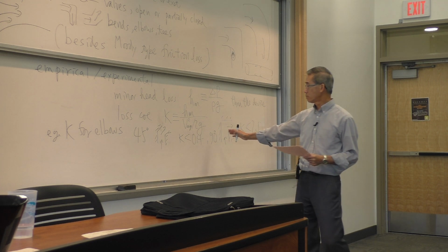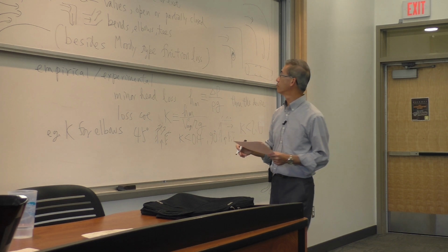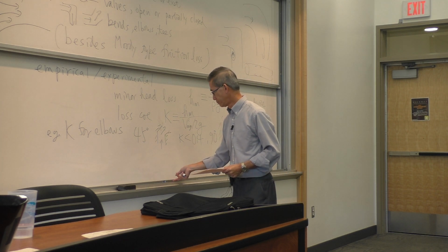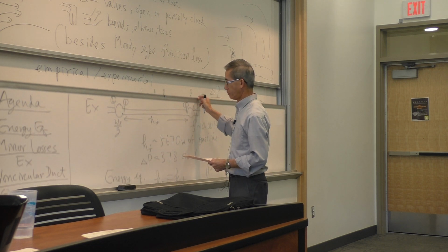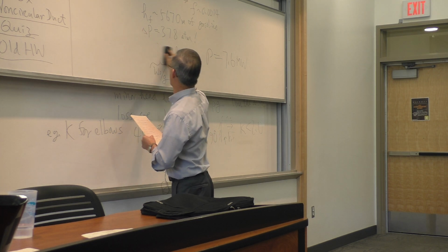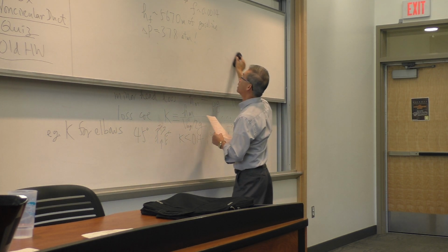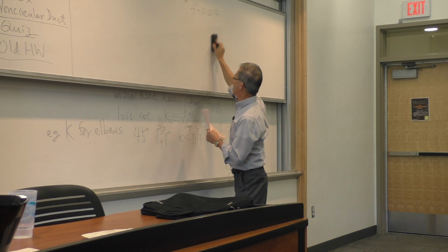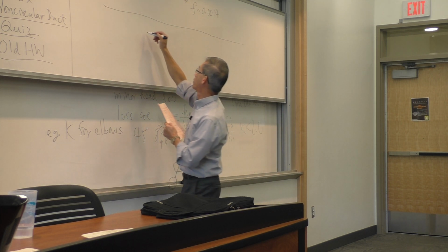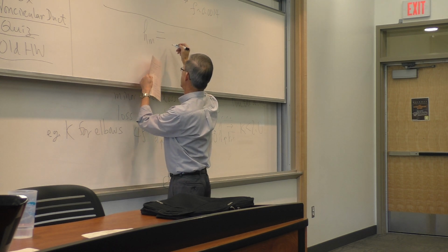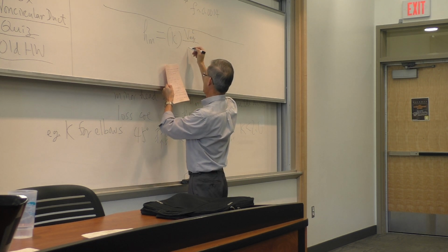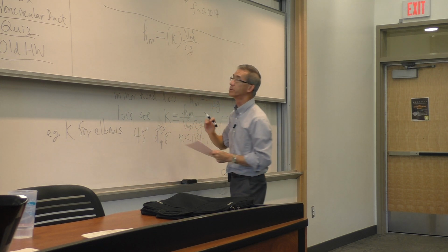So, once you have the K value, which is all that is given for that problem, and I'll give you those momentarily, the last step to close the loop, to account for those losses, will be to go back and calculate the equivalent head loss due to those components.